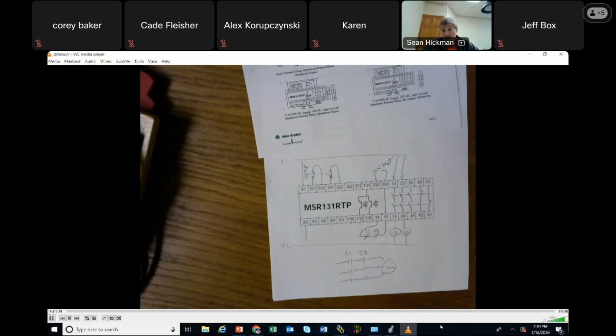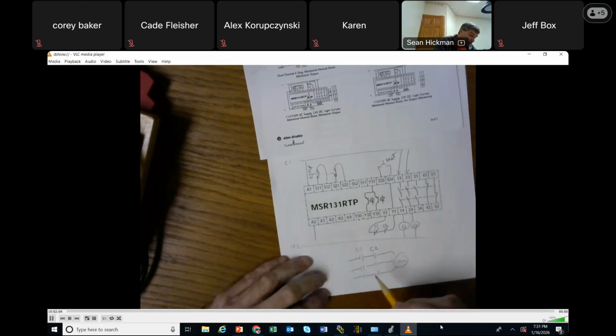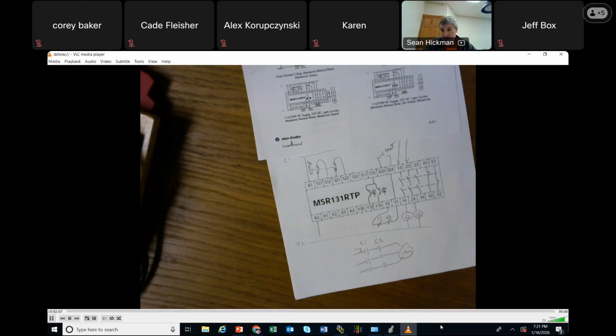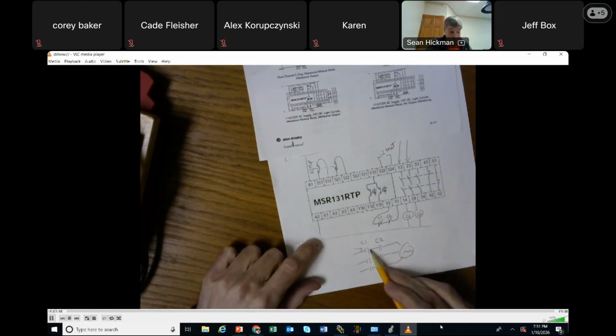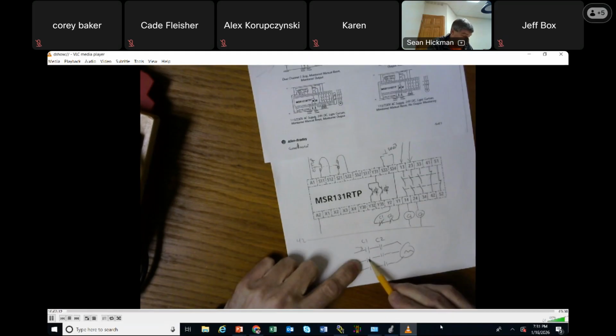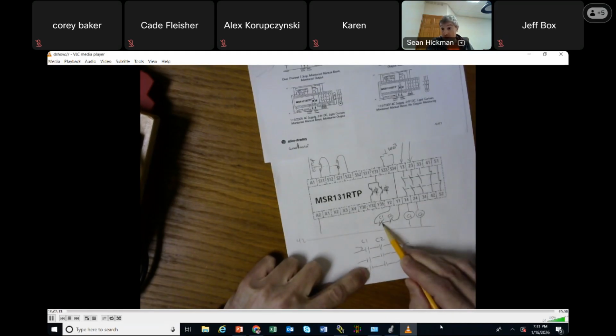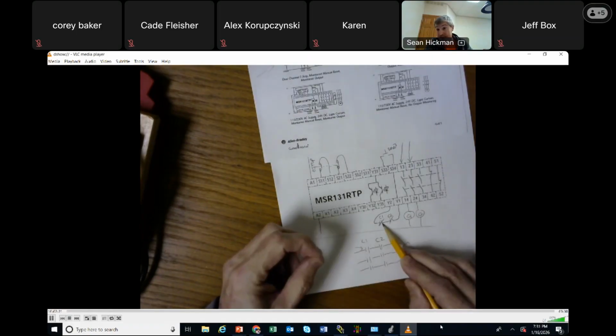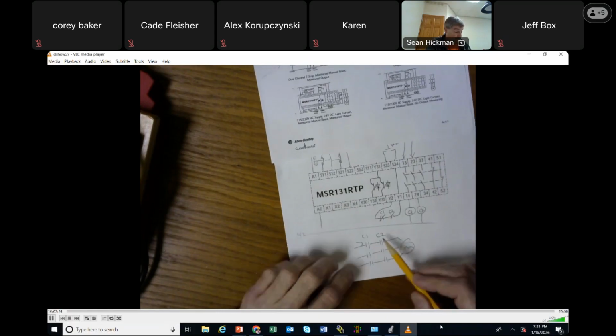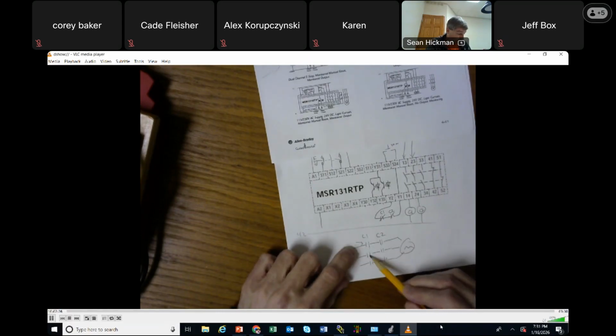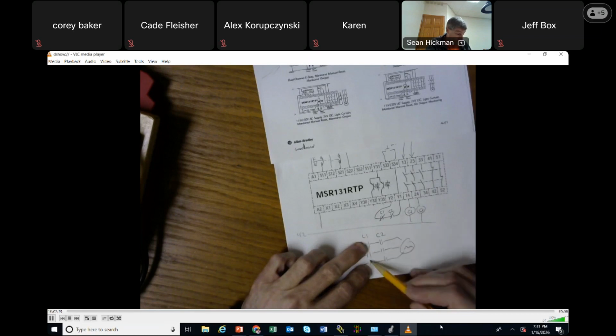So if for some reason this thing is not off, if these contacts are not, because they're positively guided contacts, in order for, if this C1 right here is closed on a safety contactor, because it's positively guided, this one's closed and this one's closed and that one's open. On a normal relay, some of these can be open and some of them can be closed if they get burnt together. But on a safety contactor, if this one gets burned on or this one or this one, these contacts are going to be closed, closed, open, closed, closed, closed, open.